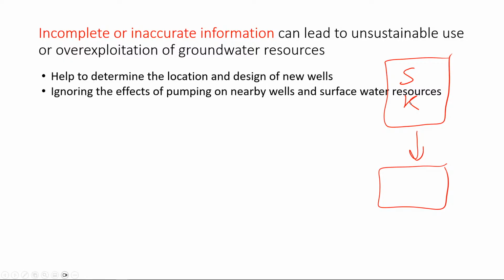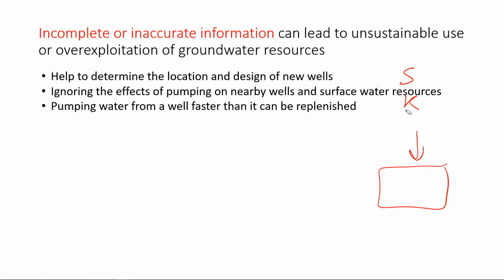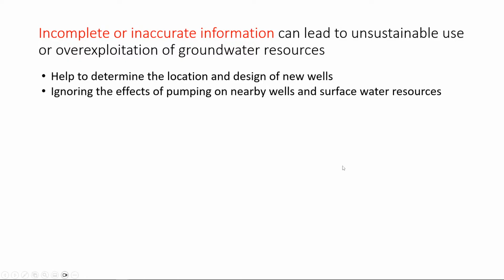So here in Florida, if you want to have a new pumping well, in the Southwest Florida Water Management District, what they will do is run this new pumping well in their existing model. So they'll have a model for the region. They will run this well with the amount of water that you need, and then they will see how this well that you are proposing will affect nearby wells, and will affect surface water resources, like the nearby stream.